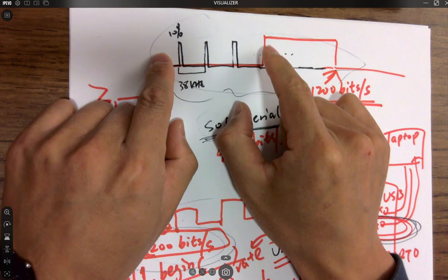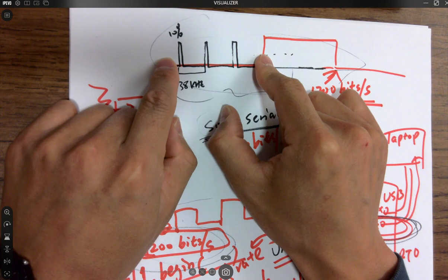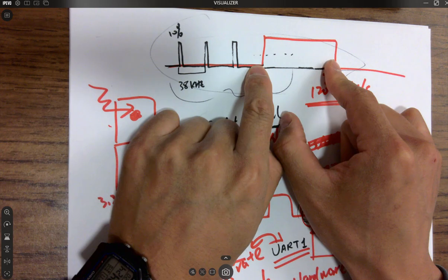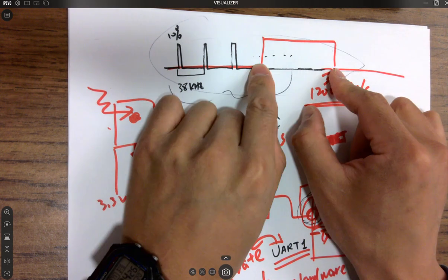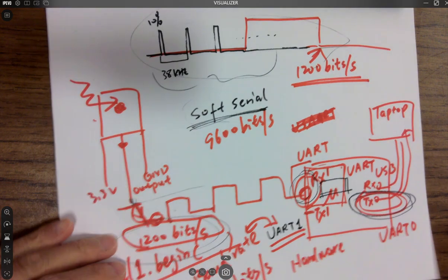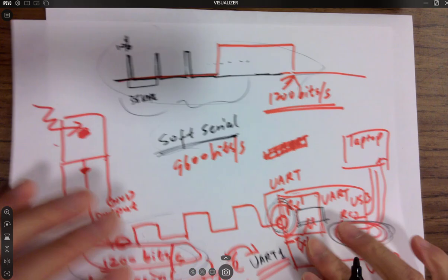So you can have a timer, to determine when you want to turn on the pulses of the PWM, and when you want to turn it off to form this baud rate. So there's a certain way of turning the PWM on and off. I explored that a little bit and found out it's not simply writing a 1.